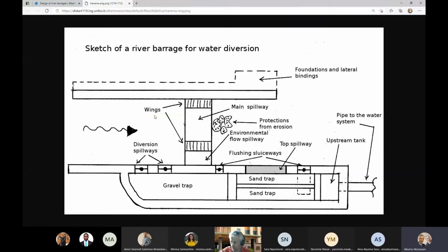So what happens downstream? This was the question. Downstream, you may have a pipe or a channel. Or it may happen that downstream there is nothing. But let's not consider this easy and trivial case. Why nothing? Because, for instance, sometimes you are able to use the water immediately without the need of transporting water somewhere else. This may happen, for instance, if you use water to produce hydropower, then it may be possible to produce the hydropower directly close to the river.